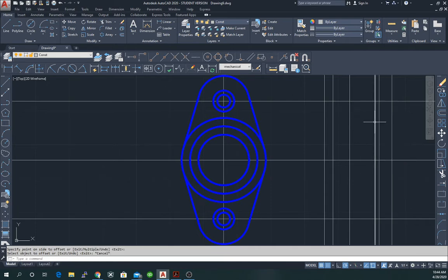Now our horizontal lines. For our horizontal lines, we're going to put a construction line everywhere where there is a relief that's happening that will result in something on this drawing. So let's start with the top here. Just click on the top, add a construction line.